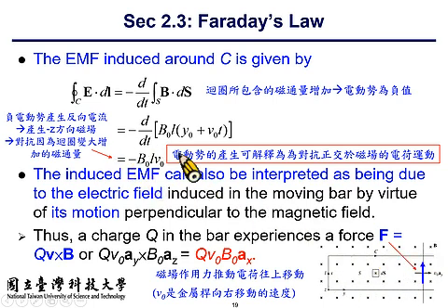So if the value is positive, then the current flow should be clockwise. In this case, we happen to have a negative value, which means the voltage is higher at the lower end and smaller at the top end. So the current flow is counterclockwise as marked in this plot.